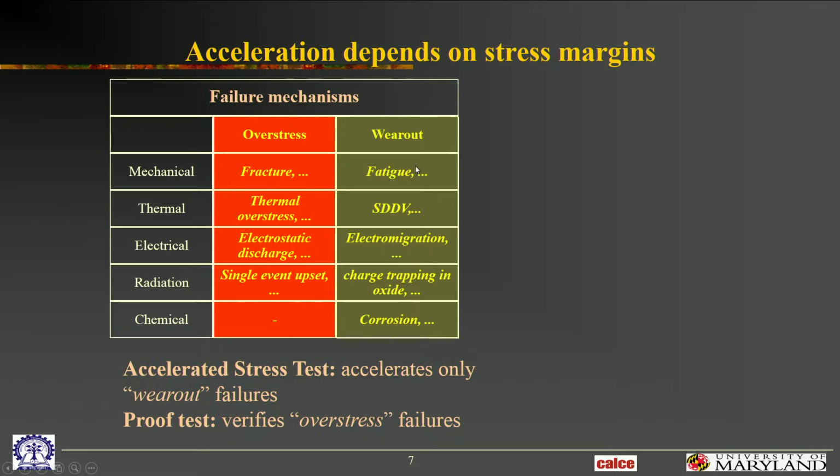Well, certainly to 85 maybe, if that's the spec, but sometimes you can even go beyond, because all that the manufacturer means is that if you go above 85, then the product may not last as long as you expect it to last in the field. Oftentimes they do have a fair amount of design margin above that. It's not going to fail instantaneously if you take it above 85, but it certainly won't last 5 years. So we do go above those spec limits sometimes, but very carefully. You have to look at the materials they've used, and see if any of them have an overstress limit at 85. What you really want to know is, where are the overstress limits of the product? Oftentimes that's not what's given in the spec. When they give you the specs, most manufacturers will derate their overstress limits and give you a safe spec limit.